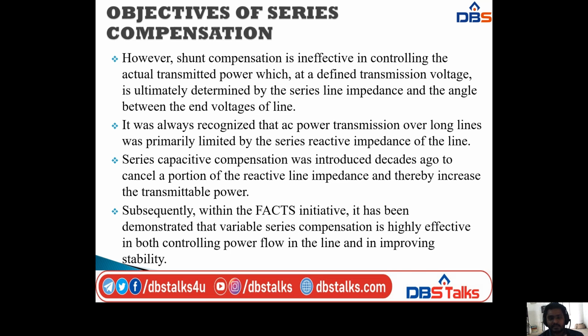So shunt compensation is ineffective in controlling the actual transmitted power at a defined transmission voltage, which is ultimately determined by the series line impedance and the angle between the end voltages of the line. That's why we are taking series compensation.